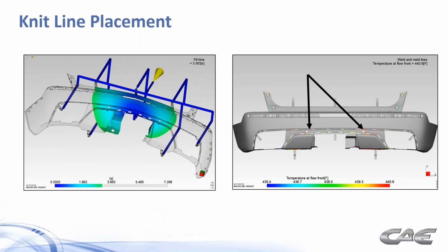So you have to account for those things as well, and that's precisely why we don't want to run our pressures right up against those limits. We want to stay well below that because we know there are things that MoldFlow isn't able to directly account for. So to correlate well with MoldFlow, you'd have to have a very well instrumented mold with pressure sensors at the right locations to be able to directly compare to MoldFlow output.